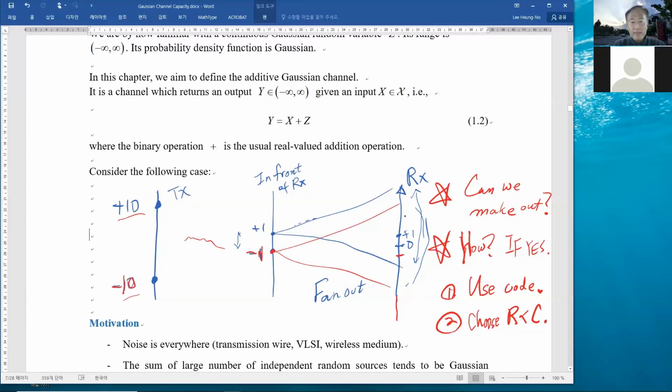Let's say, for example, in this case, suppose your received symbol value was somewhere around right here. In this particular case, what would be the decision that you make? It leans toward the positive side. So probably you would say that the plus symbol was sent. So +1 was sent, you could say.